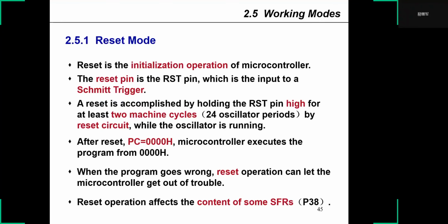Reset mode. Reset is the initialize operation of a microcontroller. The reset pin is the RST pin, which is the input of a Schmitt trigger.